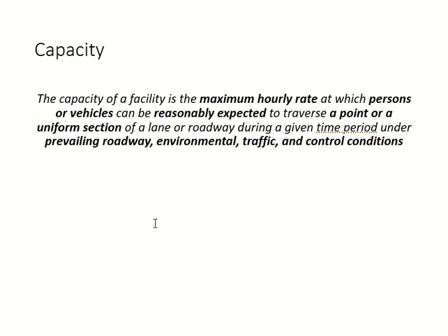Okay, and capacity is by default for a point. But if the characteristics of the point extend to the entire section, then the capacity will not change in the entire section. For example, you have the same number of lanes, the gradient, the curvature, everything is the same for all the points in a 10-mile section, so that whole section has the same capacity. Okay, but by default, it is defined for a point.